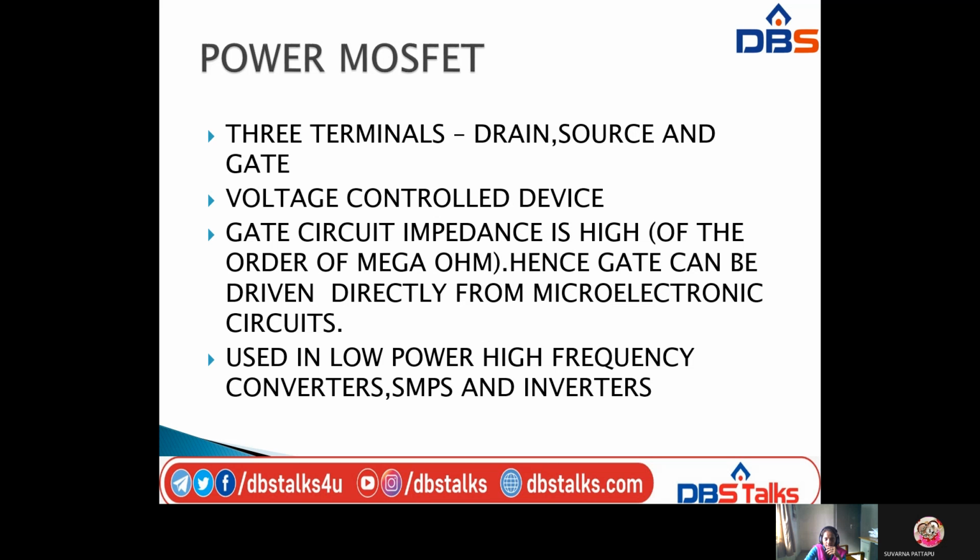So this is a voltage control device, and the gate circuit impedance will be very high, in mega ohms. Hence the gate can be driven directly from the microelectronic circuit. So MOSFET is actually used in high frequency converters such as SMPS and inverters.